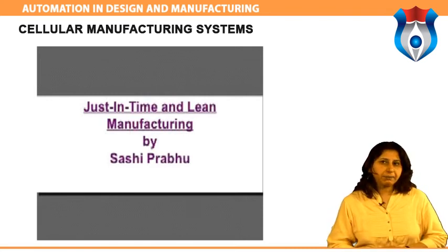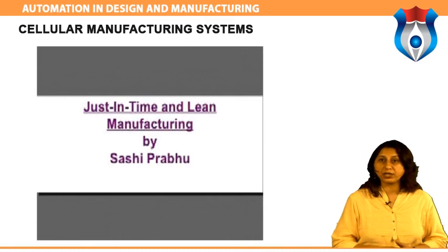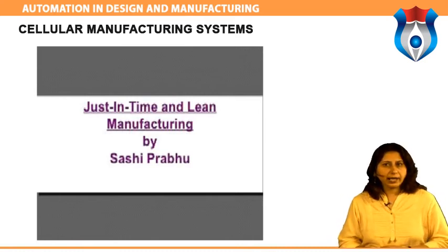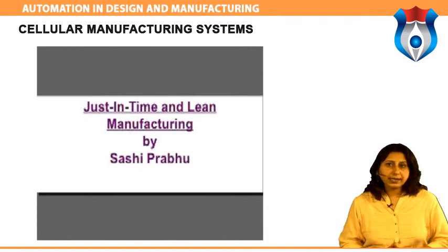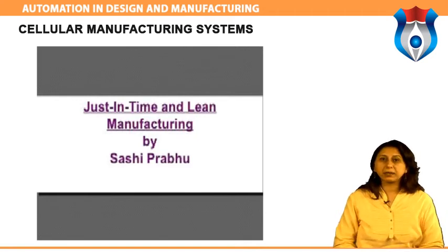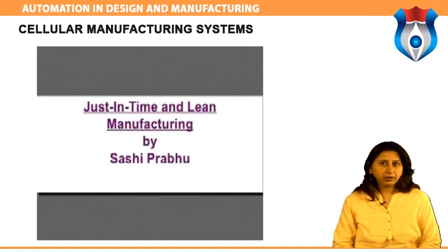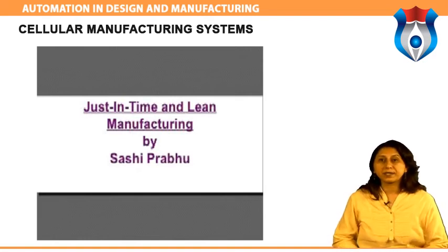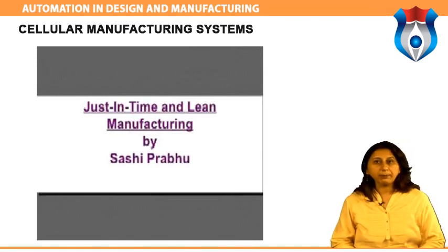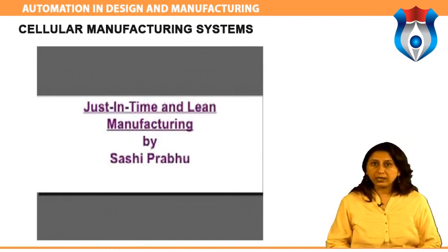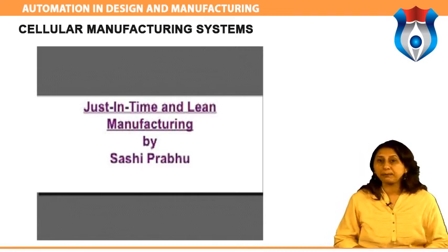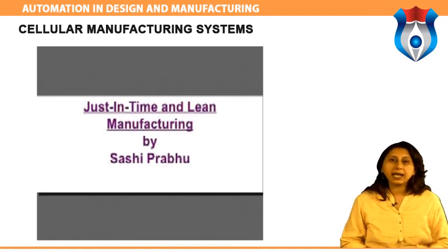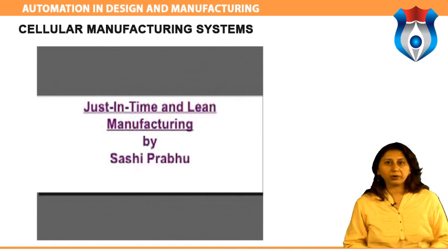The system requires companies to produce products based on potential or predicted customer demands rather than actual demand due to the lag time associated with producing goods by batch and queue functional department. In many instances, this system can be highly inefficient and wasteful. Primarily, this is due to substantial work in process, or WIP, being placed on hold while other functional departments complete their units, as well as the carrying costs and building space associated with built up WIP on the factory floor.